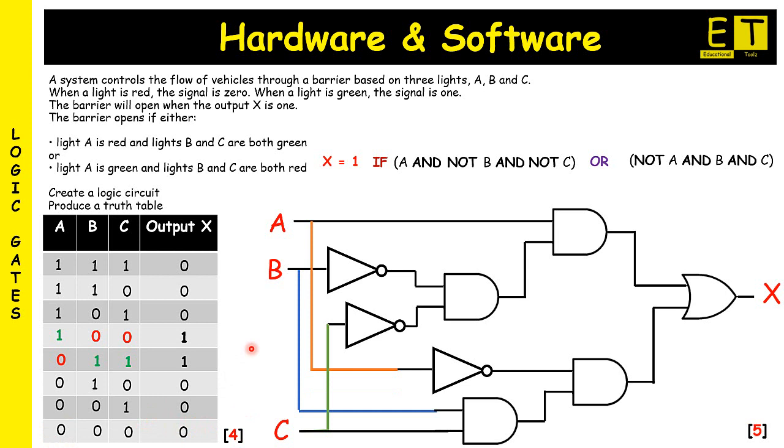So now let's look at testing this theory that we've been given. The first statement that was mentioned to us was if input A and not B and not C will output 1. So let's put that into our logic circuit, 1, 0, 0. If 1 goes in here, we'll need another 1 going in from this AND gate. As we're putting in 2 zeros, these will turn into 1s, and in order for an AND gate to be true, both of its values need to be true. So we do meet that statement. So the output from this AND gate would be 1.